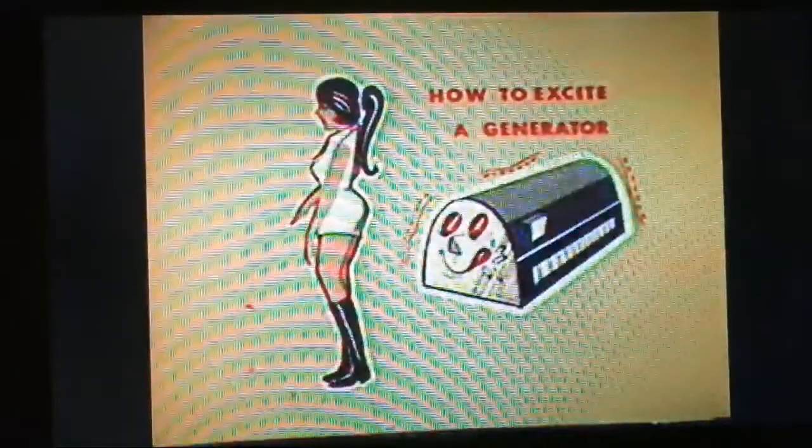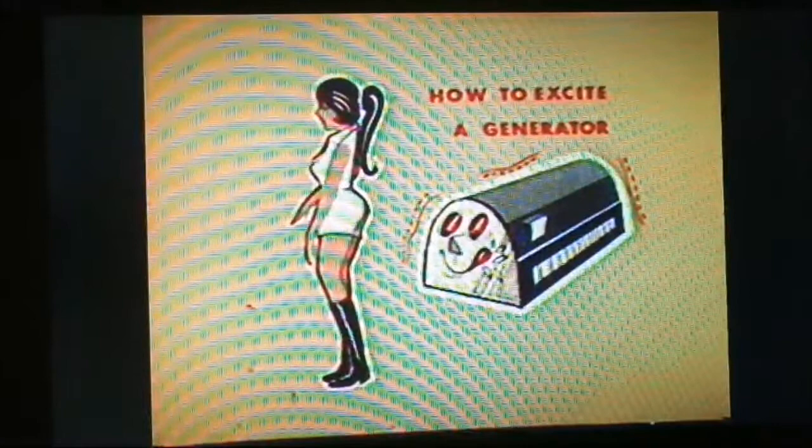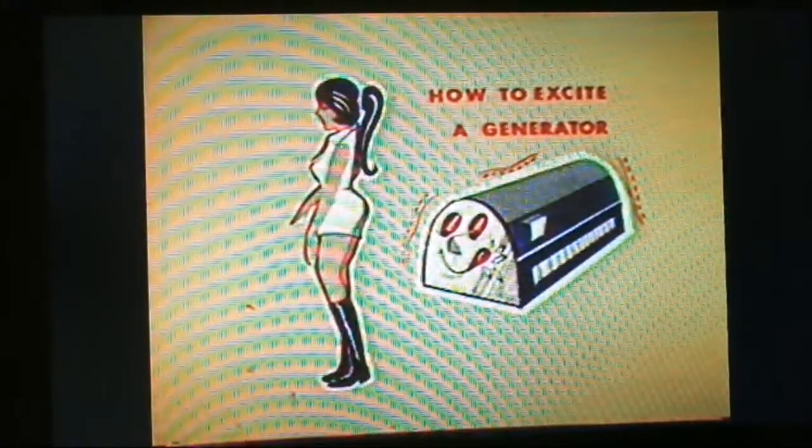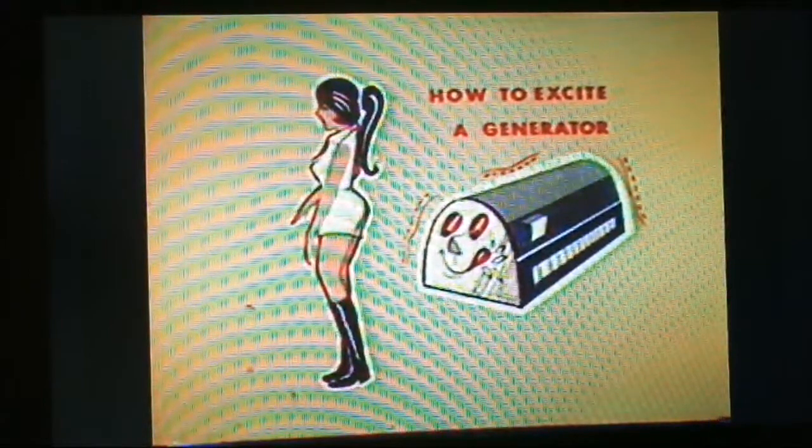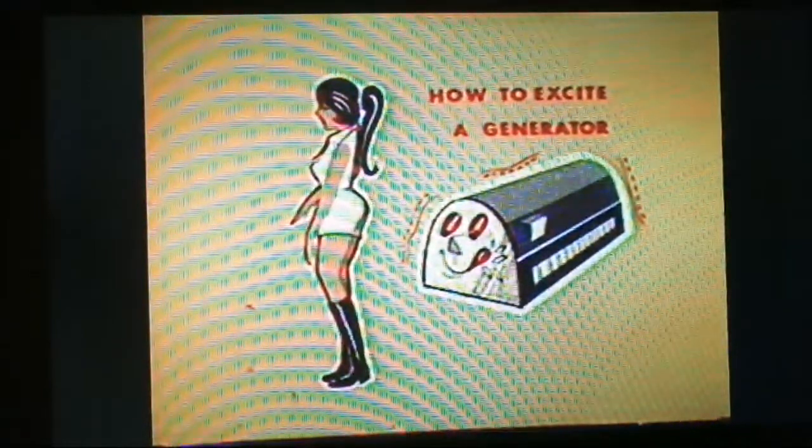It takes a lot to properly excite a large AC generator. Several thousand amps of direct current may flow in the rotor windings to create the flux densities necessary for full output. An excitation system for such a unit is one large DC generator with a series of controls and monitors capable of supplying the correct DC power level to exactly balance the AC load requirements at any given moment.